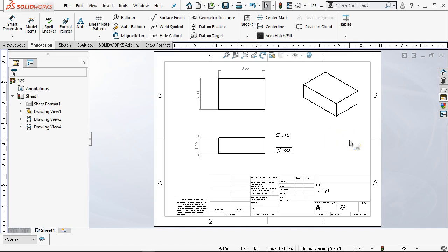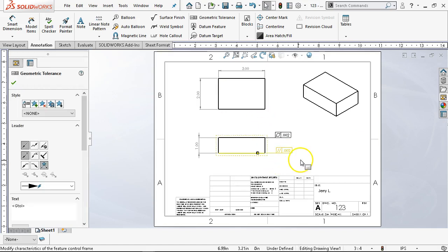All right, so taking this further, and again, I'm trying to take a lot of small incremental steps, knowing that SolidWorks isn't necessarily everybody's first language. So we'll get into more and better complexity as we go. But the next steps would be to decide how we're going to apply a datum. That's what I missed. Okay, I'm sorry, I'm getting tired. The flatness is our base. It does not get the datum. At this point, I needed a datum callout to do the parallel.